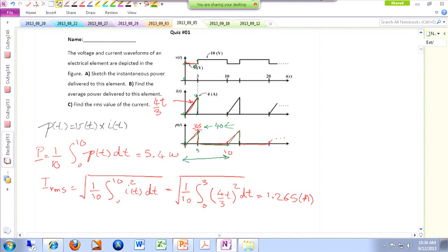Some of you gave me 3 different average values of power. One over here, then one over here, then pretty much everybody who did this approach got it wrong when they were trying to calculate it over here. So whenever signals are periodic, identify, this is your job, maybe the period is not mentioned over here, the period is 10 seconds, but you have to look at the waveforms and identify that the period of all of the signals is 10 seconds.